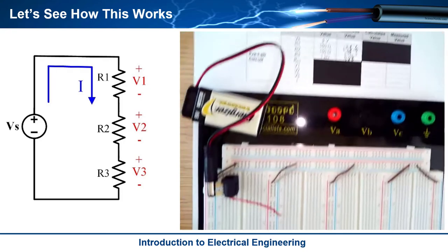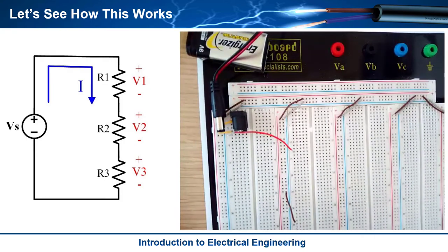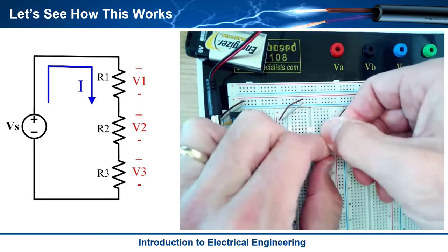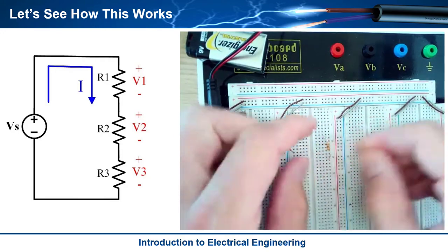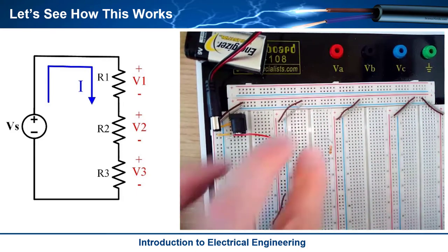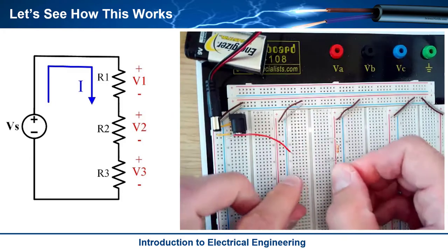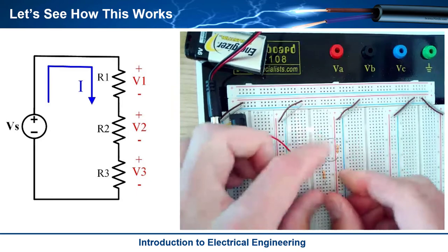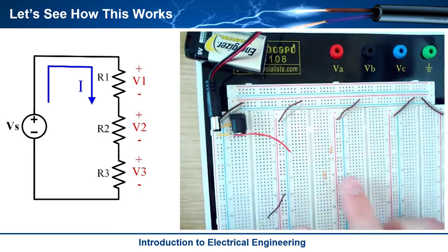And what I'm going to do is I'm going to come down here and I'm going to build this circuit. Okay, so I'm going to go ahead. These are going to be in series. So I'm going to pop that into there, that into there. And those are now in terminal strips. And then I'm going to take my second 150 ohmer, and I'll push them over so you can see it. And I'll put that like there to there. Okay, so now I got the two in series.